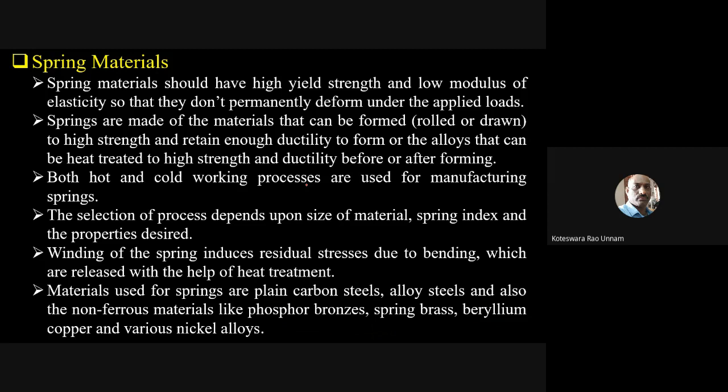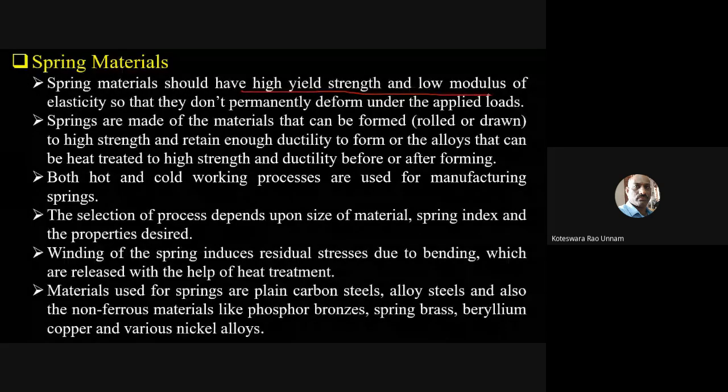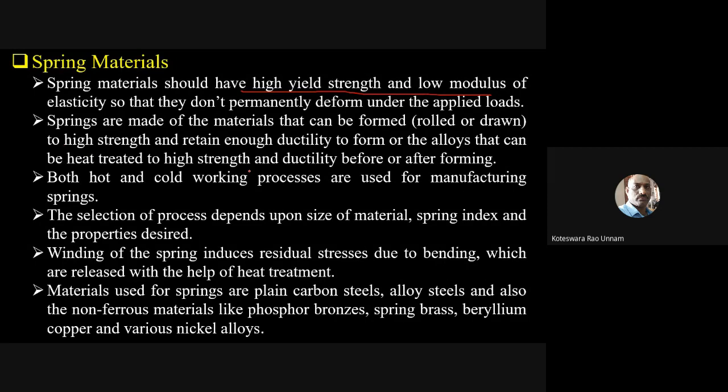So what I can conclude about the spring materials is that the requirement for any spring material is it should possess high yield strength and low modulus so that it cannot deform permanently under the application of the load, and also the spring should have sufficient ductility so that it can withstand the fluctuating loads.